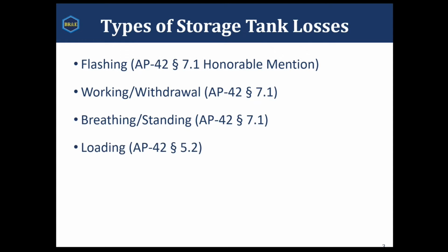We also have loading emissions. Those are vapors emitted from the tanker truck or the rail car, whatever loaded vessel, as liquid fills it. Those trucks or rail cars or vessels are not held at a vacuum. That would be rather expensive. So typically what actually happens is there's some amount of vapor sitting in that tanker truck or that rail car when it comes up to the well side, wherever it's being loaded. And that vapor will be displaced as we fill that vessel with liquid to then send it wherever it's going. So that is what our loading emissions are, those vapors that are emitted as we load that vessel that's taking our oil somewhere else.